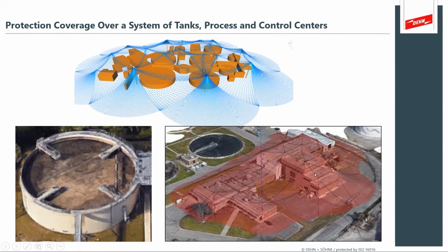But recall that each of these air terminals are driving down conductors, so you have currents entering the soil around this structure. And we talked about the earth termination system, and here we're showing the external air terminals, and this is part of that external system to avoid direct damage from lightning strikes onto these structures.